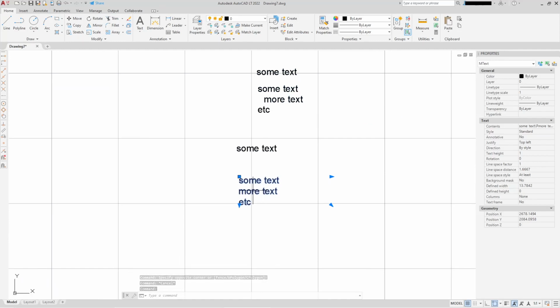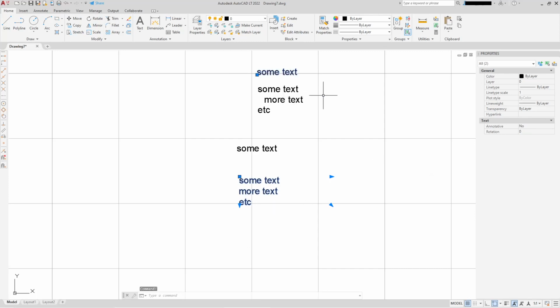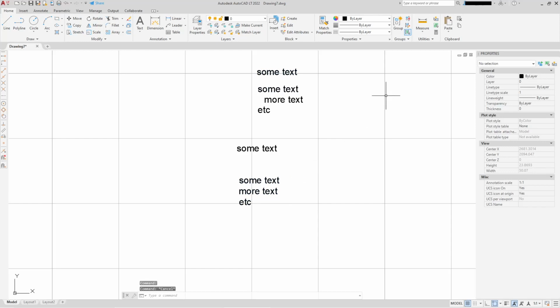I like to call it rich text because you can change parts of the text. You can change the colours of a few letters, underline, you can make some parts of it bigger and smaller, and it's still all together. Well, you can't do that with simple text, single line text. And that's why I recommend you use the Mtext over the single line.